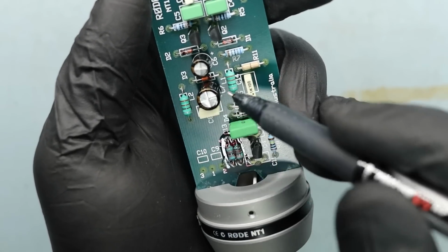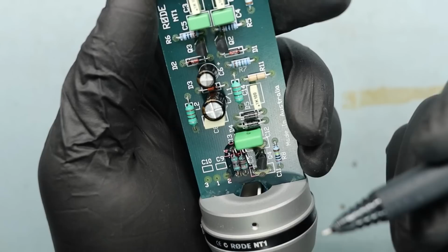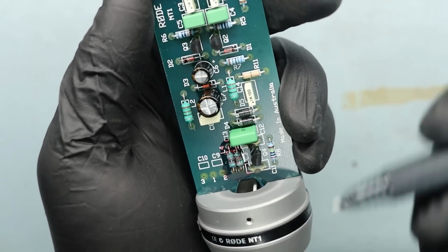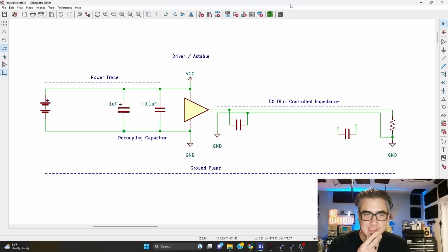And these 2 inductors here are just to keep stray, I believe, RF from getting into our circuit, or anything that we pick up from projecting it down the line. So that's about it. The last thing I want to talk about is decoupling capacitors.